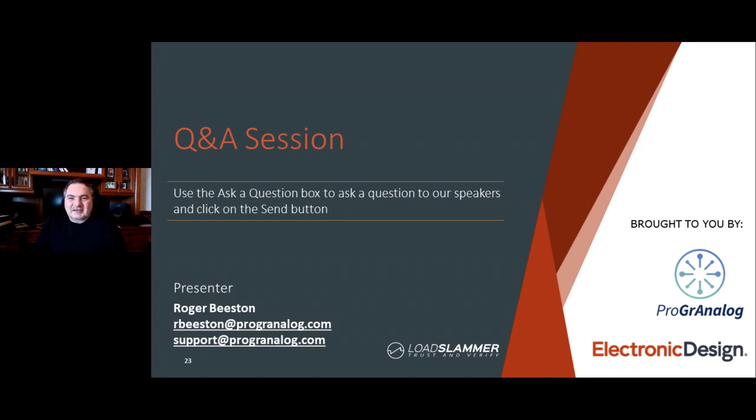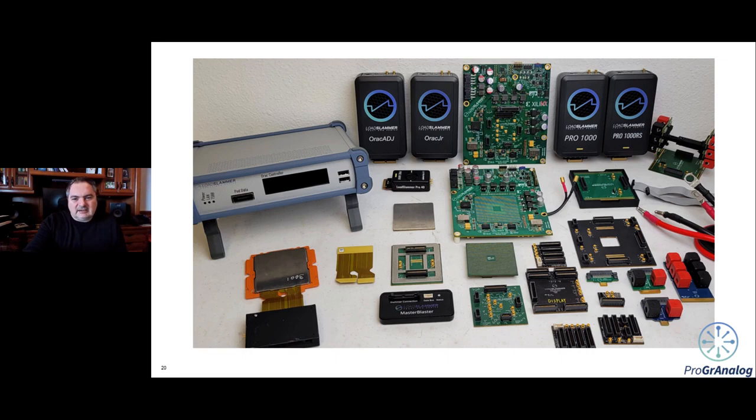Could you explain the DC load connection again? Yeah. Can I change slides? Sure. In this example, with a passive solution, you connect what we call a PTO, power takeoff unit, and that plugs into the large Samtec connector, and you can connect that to an e-load. That's what you do with a passive solution. If you have an active solution, you just turn up the DC load that you want, and it dissipates it through the active load cells.